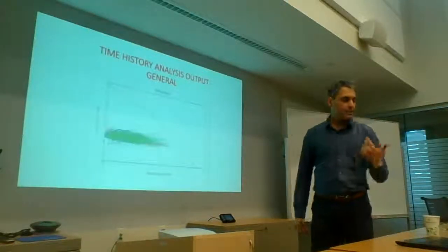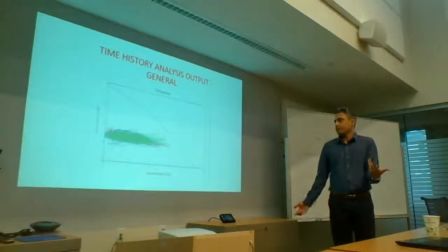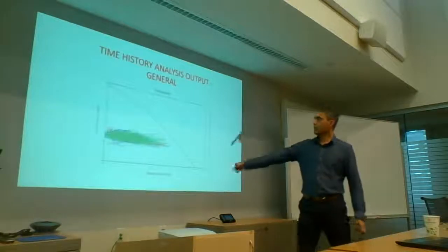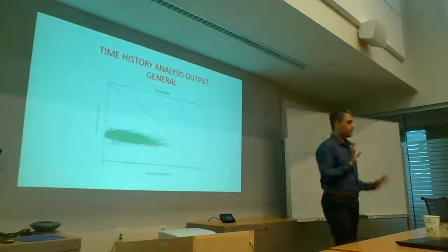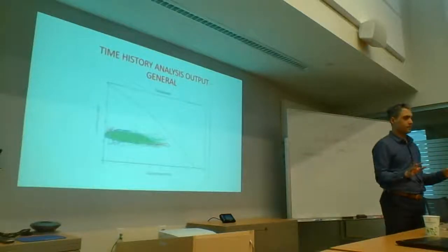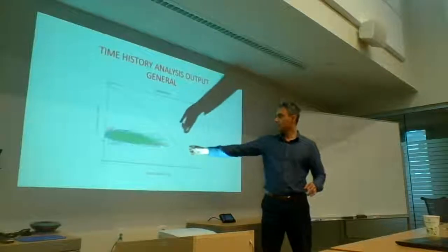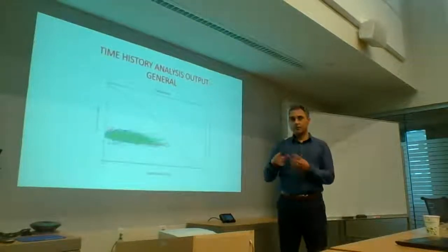Now, let's say that my performance criteria is essentially elastic. So I can plot my PM curve, where my M is my nominal expected capacity. I can draw my PM curve, and in there I can plot all the axial force and bending moment points for the earthquake.